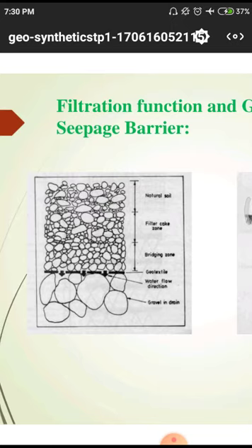And next is the filler zone. In the filler zone, normally we use different waste materials, and after that we have the bridging zone. In the bottom of the bridging zone we have a geotextile, so whatever matter or water comes from the top layers will be separated by using these geotextiles without any entrainment.